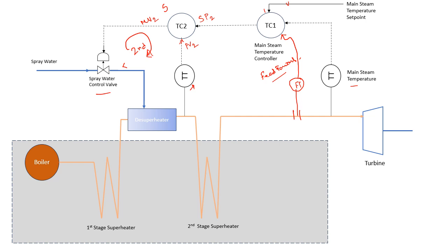What will happen is if there is a change in the flow, obviously temperature will change, but the change in temperature will take time. It will first be detected by the change in the flow. If we have a flow meter, that flow meter reading will change first.